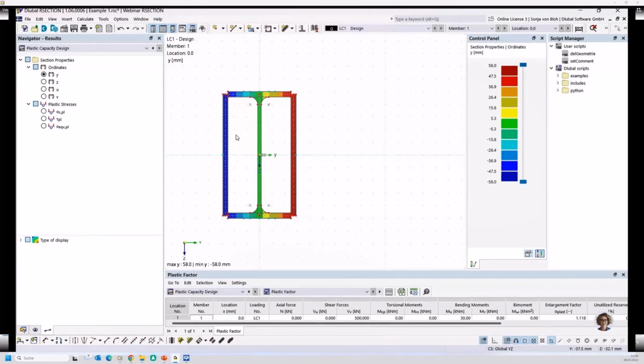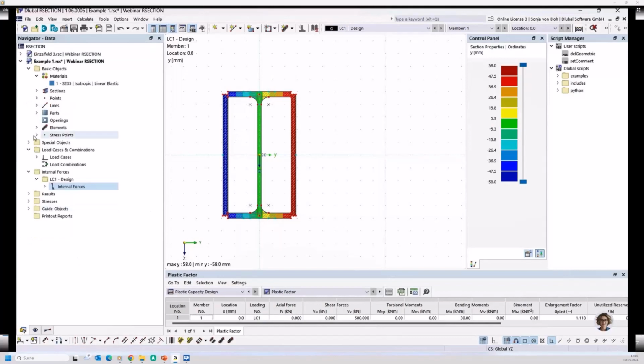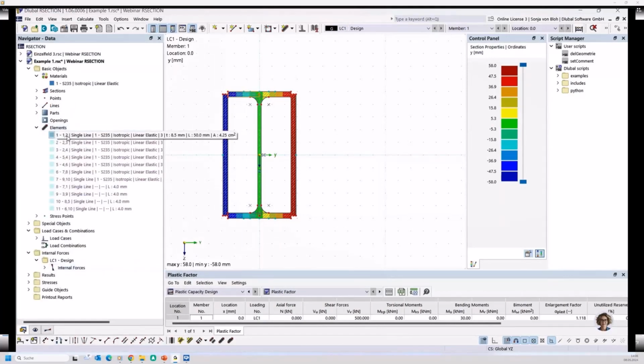However, the plastic redistribution of shear stresses only takes place if the elements are defined as well. In this cross-section elements are also defined, so the redistribution of shear stresses takes place. If no elements are defined, the shear stresses are imported from a previous elastic design. Thus, the shear stresses represent input parameters of the linear optimization, whereas the normal stresses are explicit variables for the optimization.